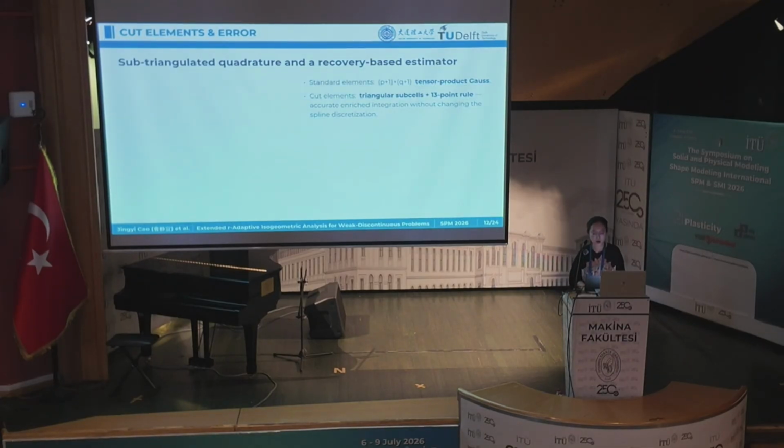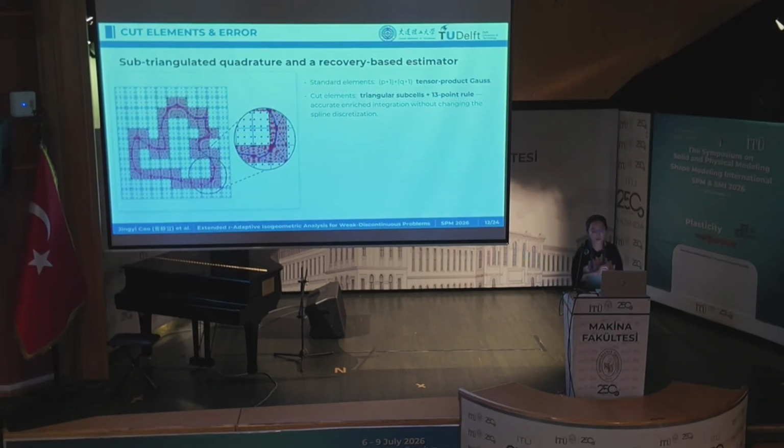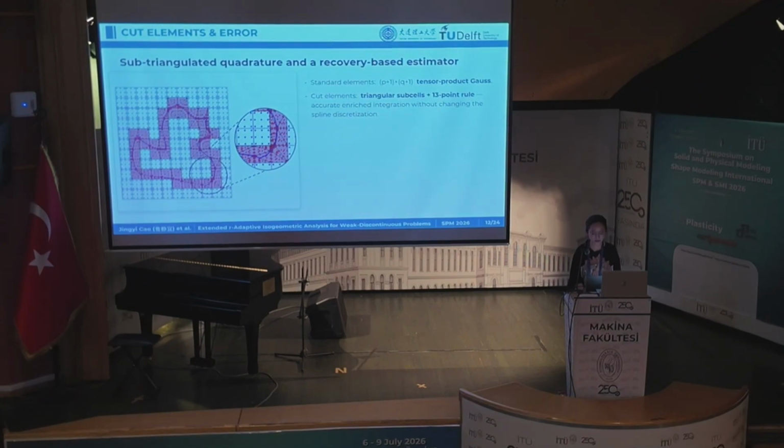So a stage of subdividing into smaller triangles is used, with 30 integration points for each subdividing triangle. The picture below shows how the integration points are distributed under this integration strategy. In the zoomed-in image on the right, the black triangles represent the sub-element divisions, and the red dots are the integration points.